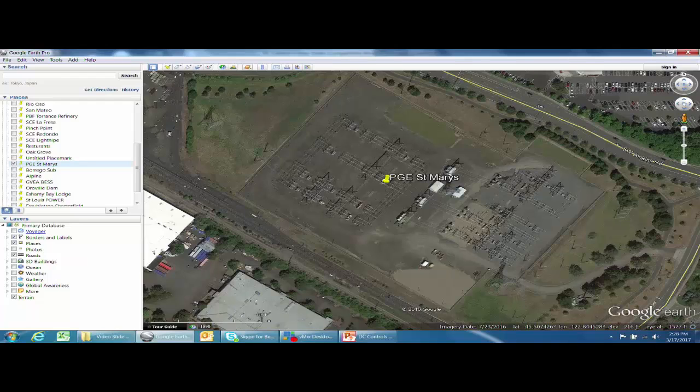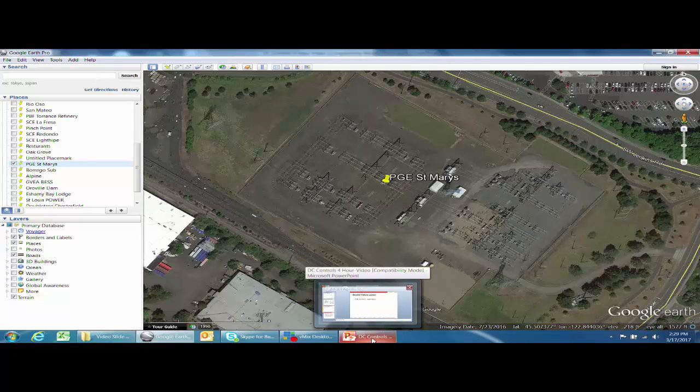Included in the facilities that were outaged were most of Intel's chip fabs, which are within just a mile or two of this substation, and Nike's headquarters, which is also about 2 miles from the station. Really unfortunate thing, and it hasn't happened again since. I'm sure they've taken additional precautions to prevent this, but it illustrates what can happen to you if your breaker failure scheme is subject to a testing error and you've put a common point of failure into your design.